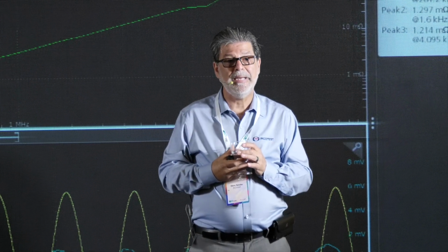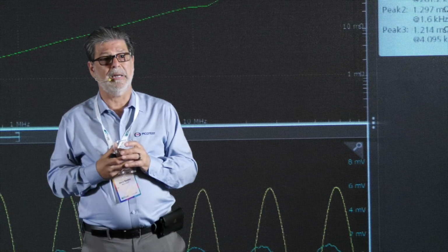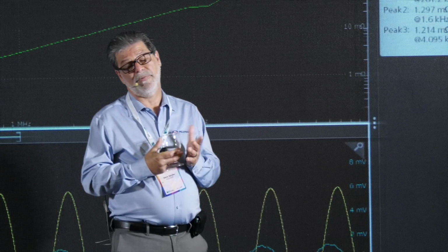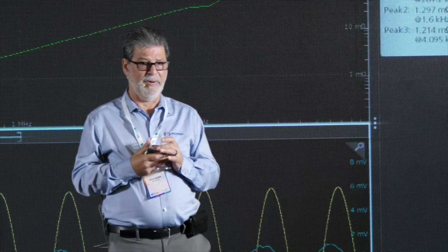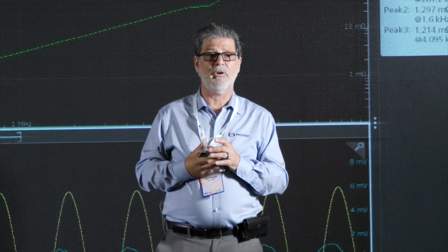How do we measure the PDN? We measure the PDN using our own 2-port probes on a vector network analyzer if we have the board. Very often we don't have the board, we just have the simulation files. If we just have the simulation files, then we connect our VRM to the board.